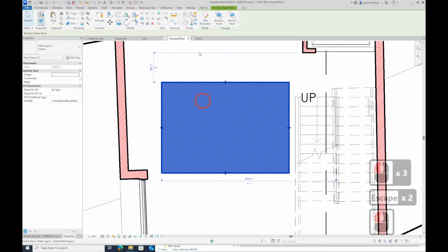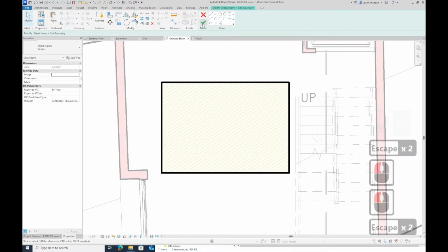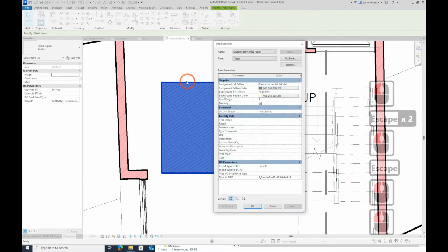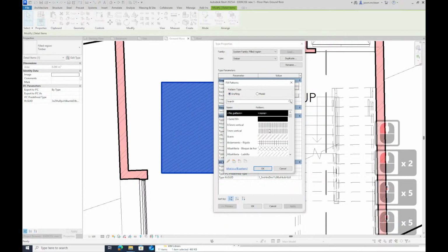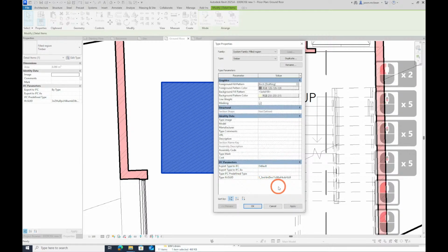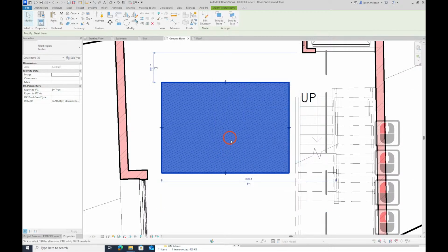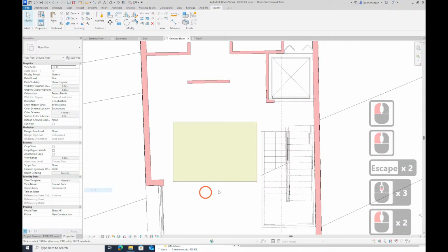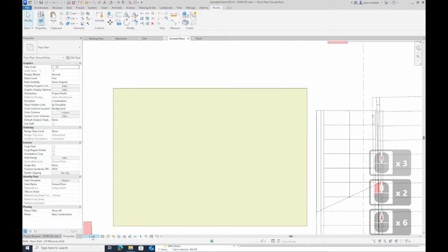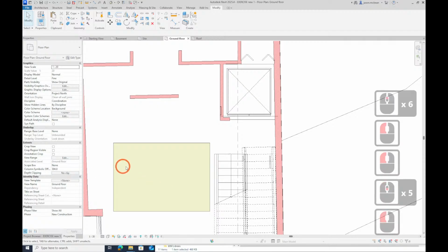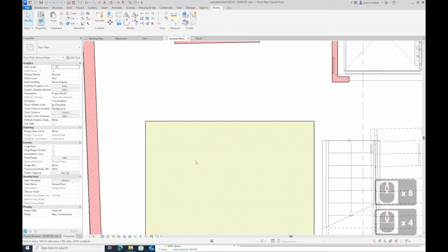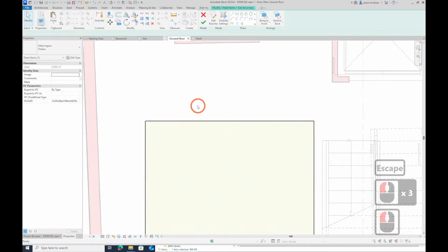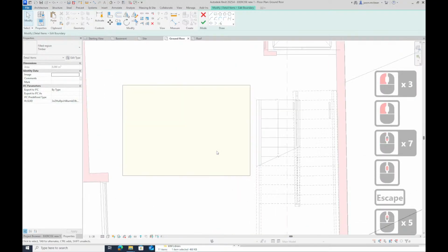If I go to fold region and say edit, this is where there's a problem as well, and this is a Revit thing. If you go to drafting and you pick a weird pattern, birch, you have no control because this is dependent on the scale of the viewport and it has no other function. You can't rotate it. These hatches in Revit are very strange as well, and they're complex to make. You can make them, you can write code to do them, but it's tough.